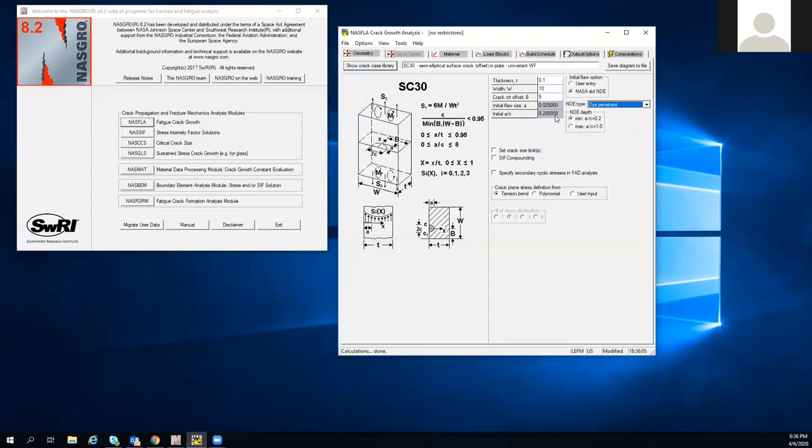So if you have a finite element analysis or a hand calc that tells you the highest stress, or the peak net section stress of your part, I'm going to assume a flaw is oriented at that location such that that stress is going to open that crack. That is the typical standard across multiple industries in order to perform fatigue crack growth calculations.